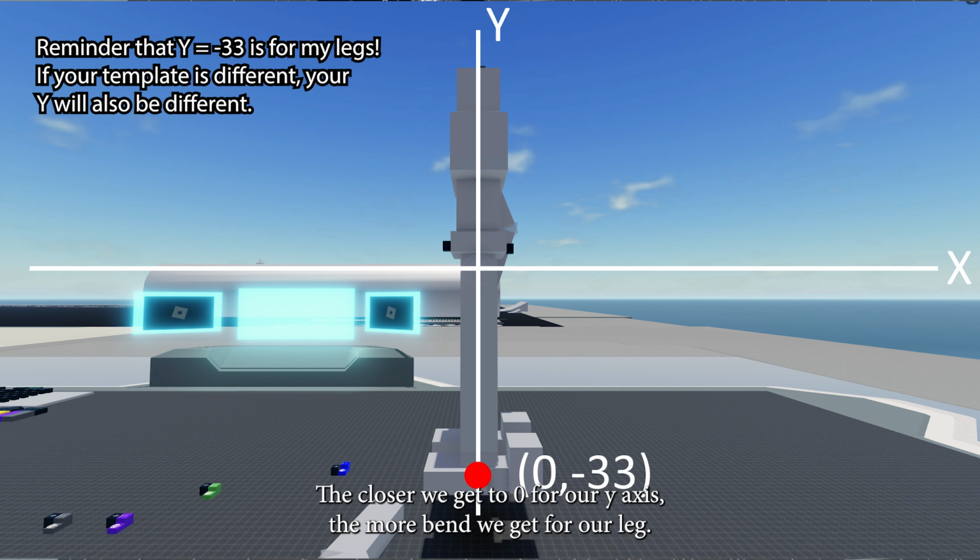Now for activating the switch boxes, we're going to use a keybind with a hold configuration on and change it to a keybind for running. I like to use left shift. Now connect the walking heights, lengths, and animation speed to the off inputs of the switch boxes. And after that, connect the running heights, lengths, and animation speed to the on inputs of the switch boxes.